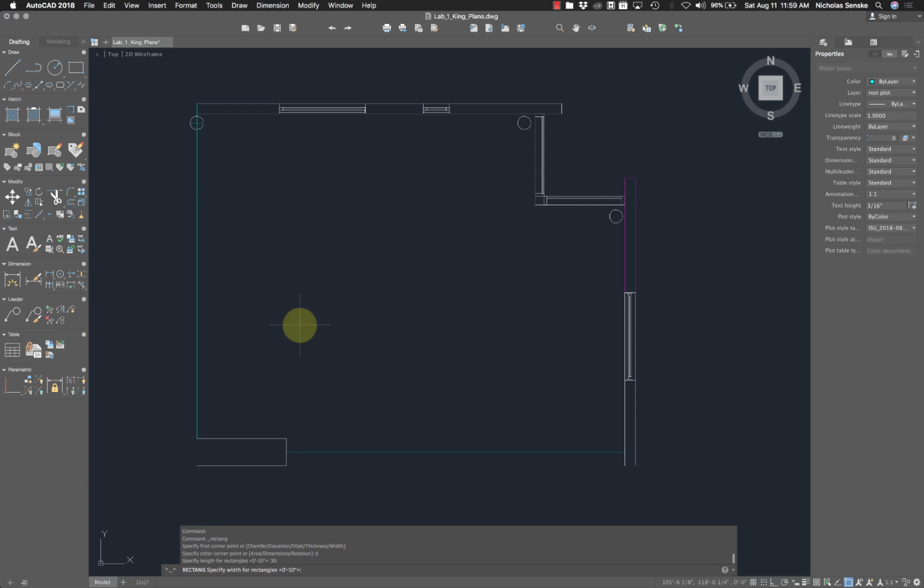The other way you could do it is to say that the width of it is 60 inches. You could also say that's 5 feet. So 5 and then the little apostrophe, 5 feet. So there you go. You can do dimensions in inches, you can do dimensions in feet, and you can also do dimensions in feet and inches. So I could have done 5 foot with an apostrophe, 5 inches, and then with the quotes. So for example,